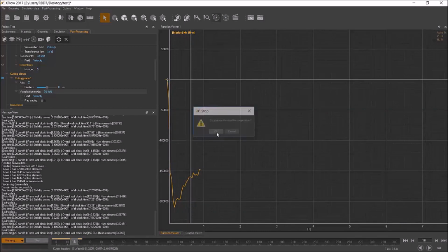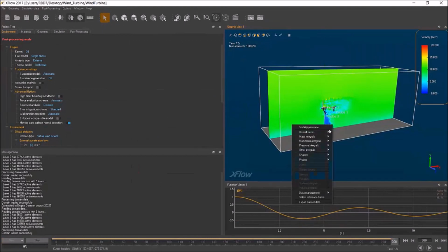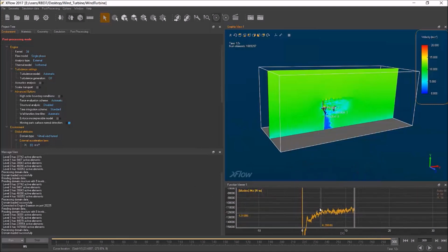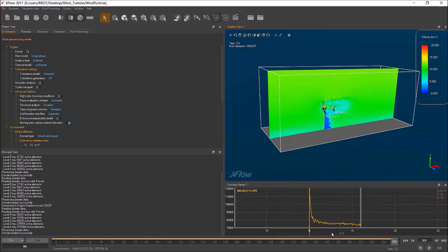And yeah, I think I'll just finish by showing you very briefly the results of the simulation when it's done, because I don't want you to wait for the simulation to end by this webinar. We're already short in time, so I've got here the final solution run, and you can see this data of the blade, for example. So MX, you can see the MX is converging towards some values around minus 110 Newton meter maybe, and the different forces acting on the blade as well.